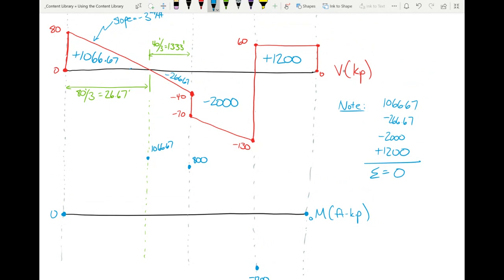See how the shear diagram kind of looks like that? We have a lot of shear to a little shear. See how the magnitude decreases? If the magnitude decreases like that, that means your slope decreases. So you go from a lot of slope to a little slope, and that's going to be your moment diagram value right there.